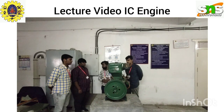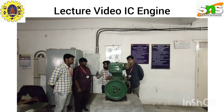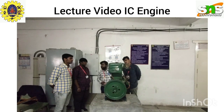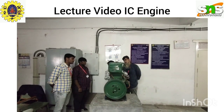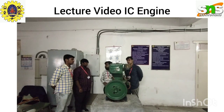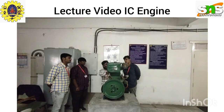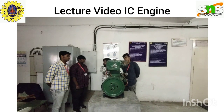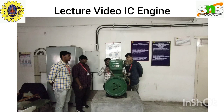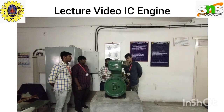Then the clearance volume. The clearance volume Vc is the space created when the piston is in the top dead center position. Then swept volume is the space or volume created by the movement of the piston from one dead center to the other dead center. So these are the terminologies of IC engines.